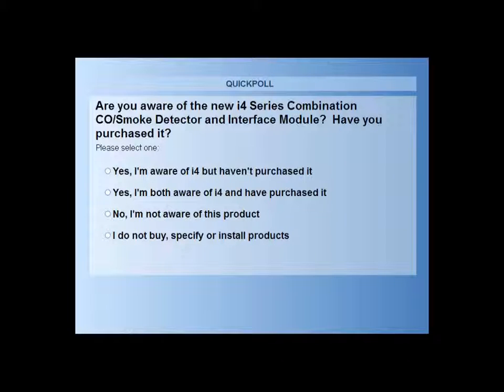And guys, we do have a couple more questions we'd like to ask live here. Doug, I think the next one's for you. Let me just read it. In the combination detectors, when the CO alarm goes off, if you have multiple combo detectors, will all sound? So will all sound CO? I guess that's an interconnect question. Yes, they will all sound. So when one goes into alarm, the sounders will activate on all in a temporal 4 code. Even the i3 smoke detectors that have sounders and are connected to that loop will sound in temporal 4 as well.